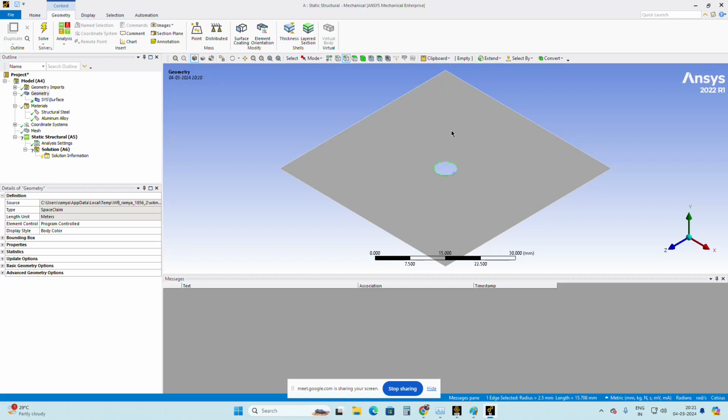This is what we did 5 or 6 years ago, when automatic meshing and such things were not yet developed. In Ansys Workbench, it gives options so that without splitting the surfaces into multiple surfaces, we can get smooth meshes. Without converting the parametric surface into a biparametric one, you can achieve a quality mesh here.